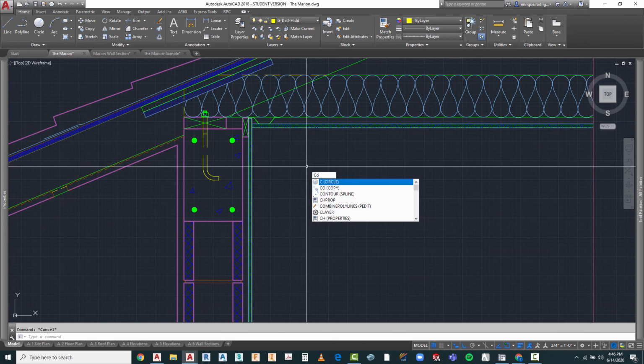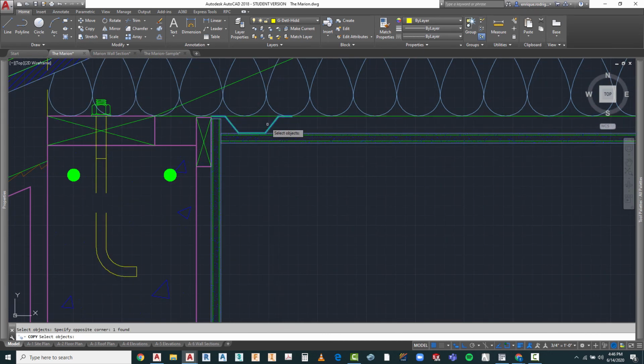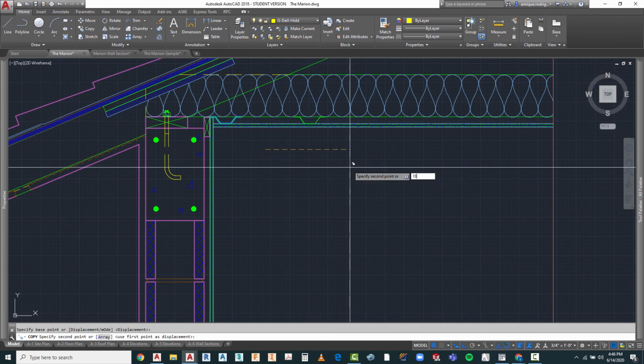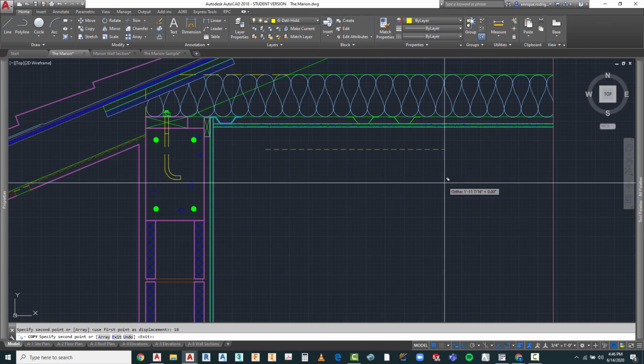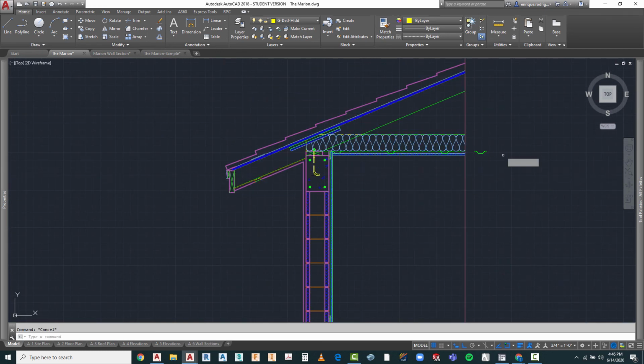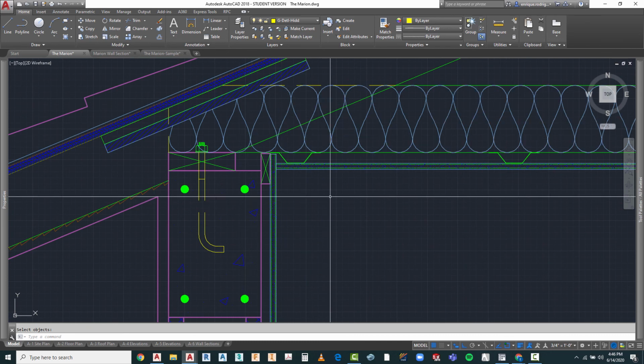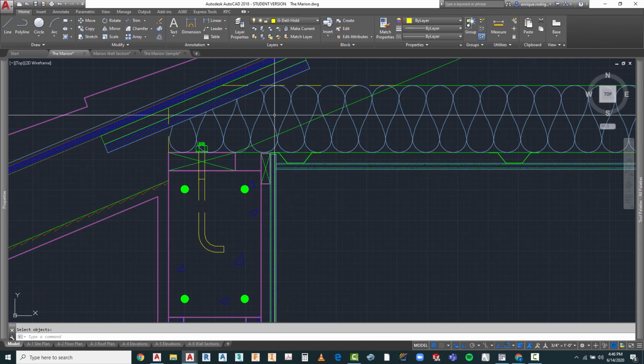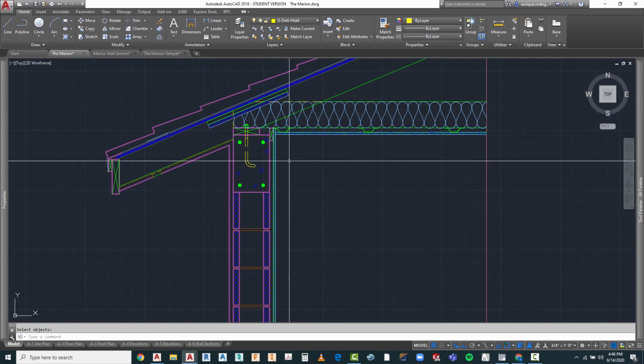Now, I'm going to make sure also that this is spaced at the 18 inches that I talked about before. So that's 18. I can copy it again at 36. And I would copy it again at 48, but that's going to be beyond our cut right here. So now we have the top of our ceiling located in here, and our wall finishes located in there.